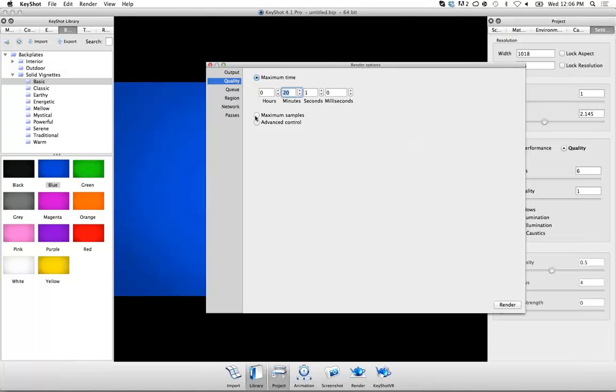Another kind of simple way of controlling your quality level you're rendering is clicking maximum sample. Right now it's at the 32. You can increase or decrease that to increase the quality of your rendering. I'd be very wary of maxing it up like this. Don't do this usually. I would say incrementally increase until it reaches a level where you're happy with it.